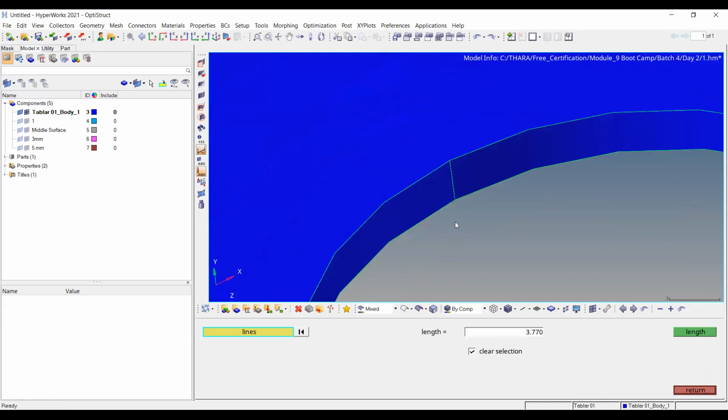See, the thickness of this component is very less. It is 3 mm thickness. When the thickness is within a certain range, for example between 10 or 12 mm, we are going to extract the mid surface. The number which I am mentioning here is just for an example. It is not specifically meant for 10 mm only. It is not like that. For example, I'm saying, if we can extract the mid surface, then we can go with the 2D meshing.